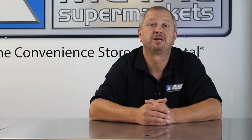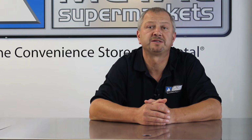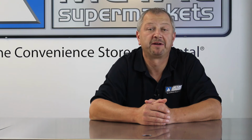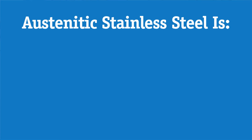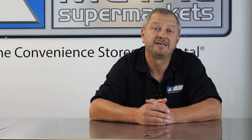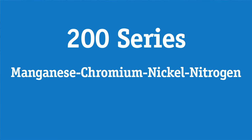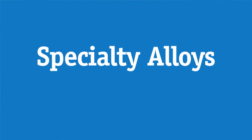Austenitic steels make up the largest portion of the global stainless steel market and have a wide range of applications such as food processing equipment, kitchen utensils, medical equipment, and more. Austenitic stainless steel grades are weldable, non-magnetic, and not heat treatable. Typically, austenitic stainless steels can be loosely divided into 3 groups: common chromium nickel, which is the 300 series, manganese chromium nickel nitrogen, which is the 200 series, and specialty alloys.